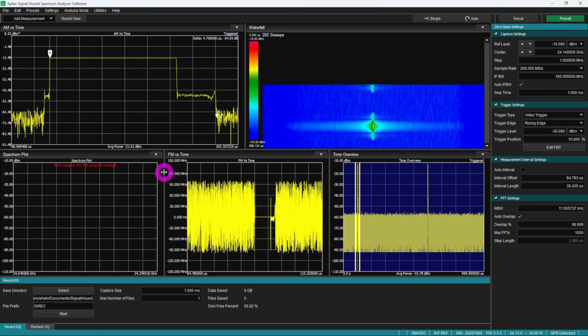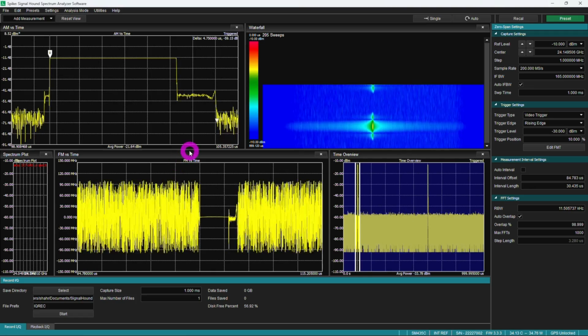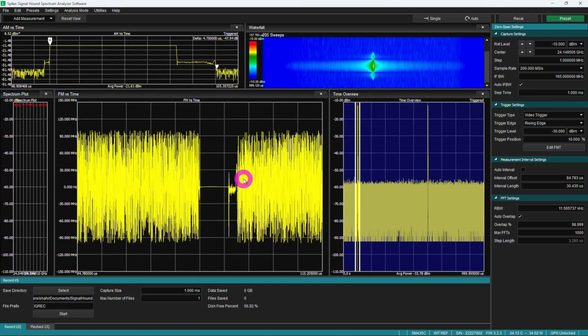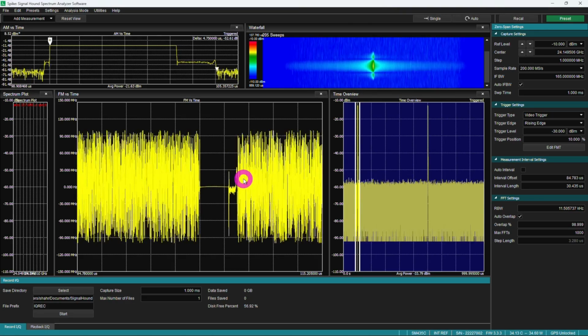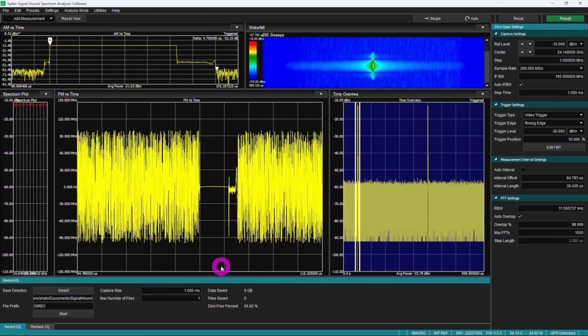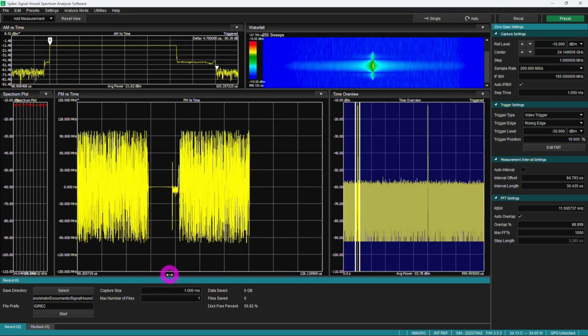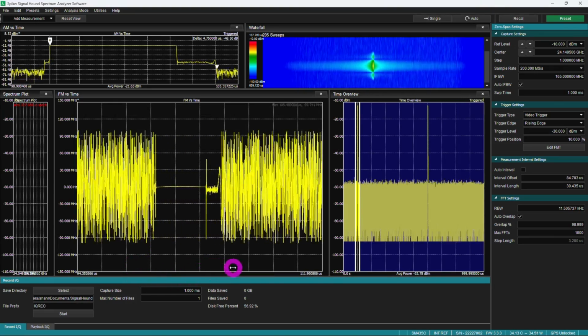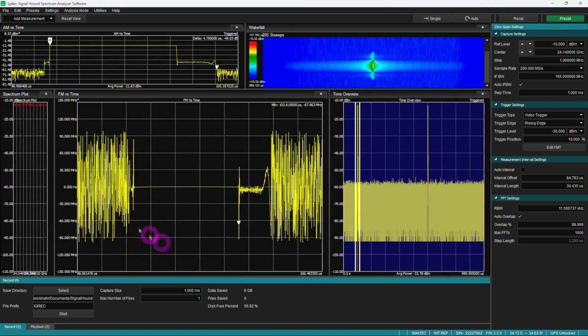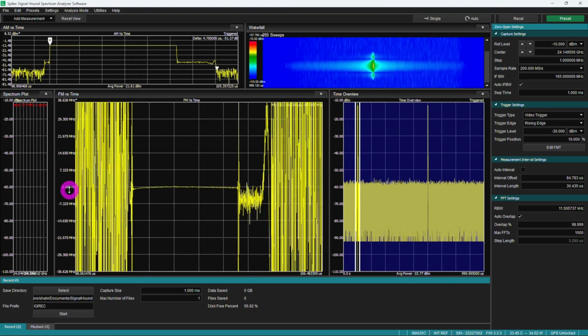But I'm also very much interested in seeing what happens to the frequency, because that is a pretty important characteristic of a radar, and you don't want it to go outside of the ISM band where it is allowed to transmit. So let's go ahead and zoom in here. So this is a very large frequency range we're looking at. We can do the same thing and zoom into this one as well. I think the rotation of the wheel seems to be anti-intuitive. It's backwards to where I would expect it to be. Yeah, I always turn it backwards first.